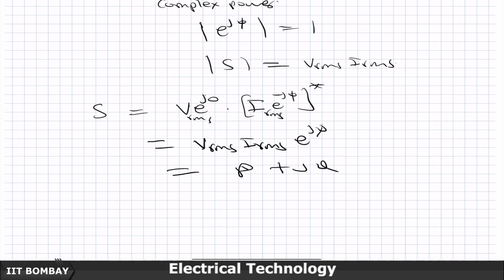So, therefore, for the complex power, now remember, do not get confused about why I did not just write it as V times I, why I wrote it as V times I star. That comes from the convention that the power consumed by the inductive element, the lagging element, has to be taken as the reactive power consumed. Consumed is just an English word here.